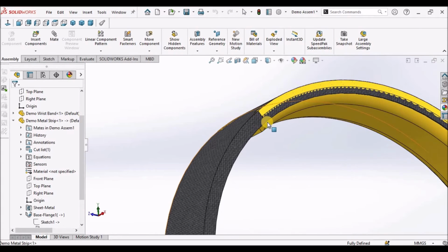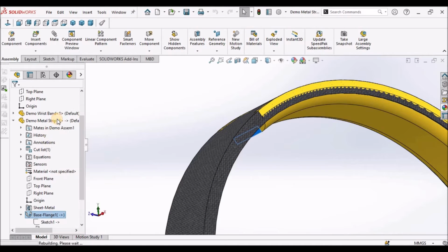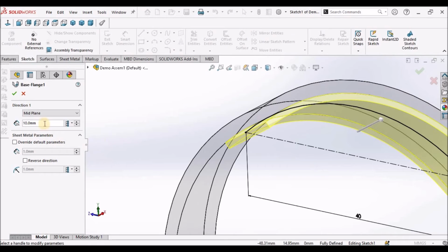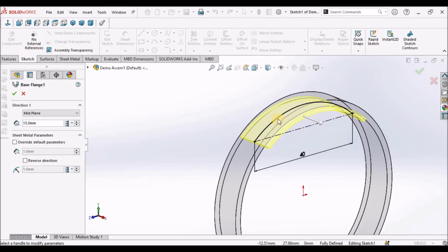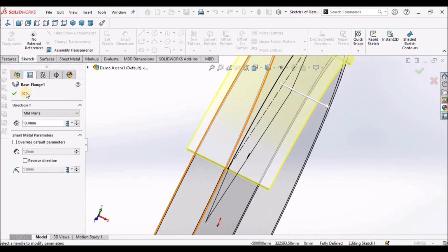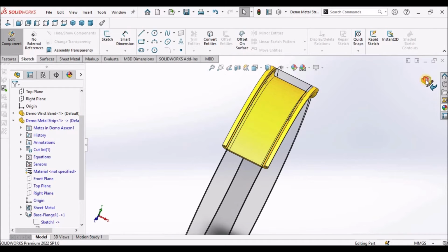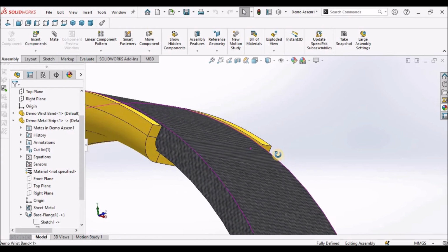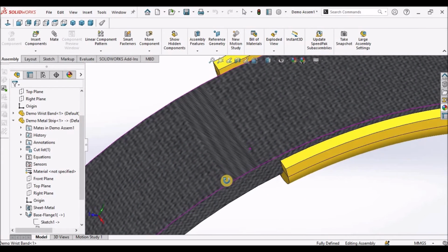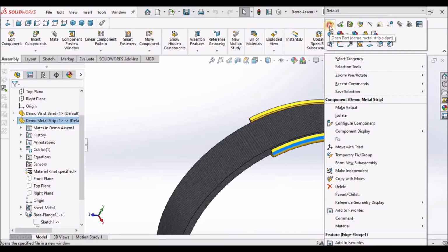See, it is merging with this. So in top down, what we can do is we can edit this. I had intentionally taken 10 mm, now I am going to take 13 mm to increase the width. See here. Come out of this assembly mode. See here, now it is exactly matching. Now once again open this file.